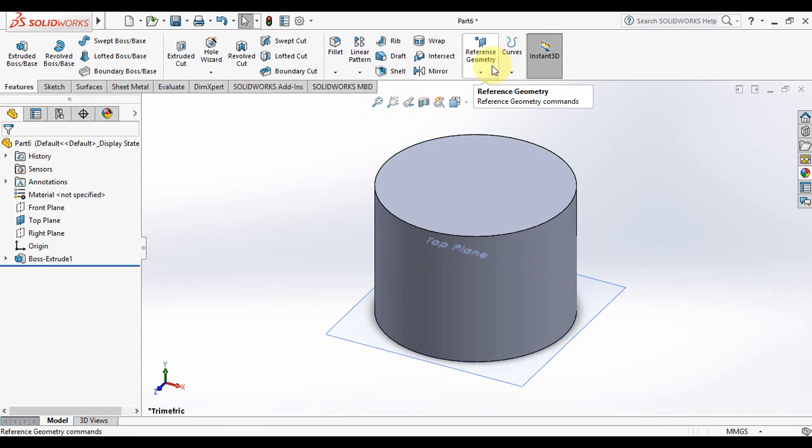So to create different planes, the system requires references, and as you can see, every time you open Solidworks as new, you have at least 3 planes. You can start drawing on each of the planes depending on the need that you have. But if you need to draw somewhere else in a different position, place, whatever, you have to be able to create new planes, because as you remember, Solidworks always has to go from 2 to 3 dimensions. And in order to make something in 2 dimensions, you need or a plane or a surface. You cannot draw on the air.